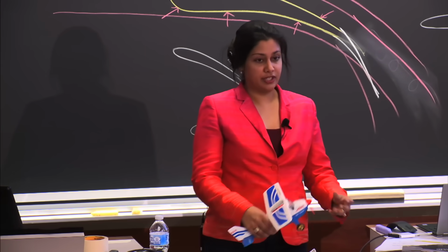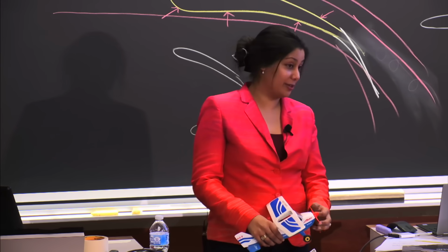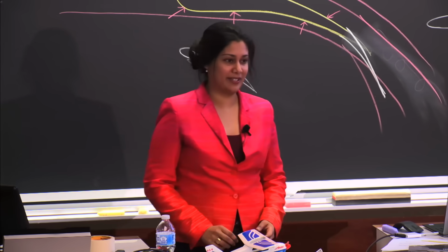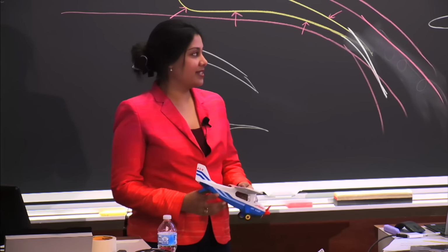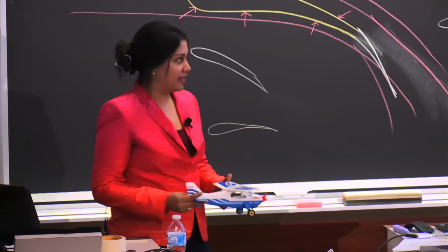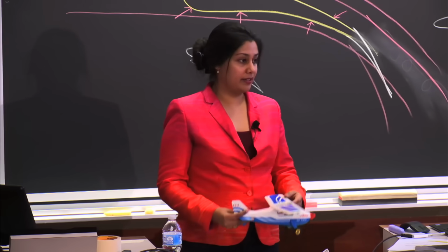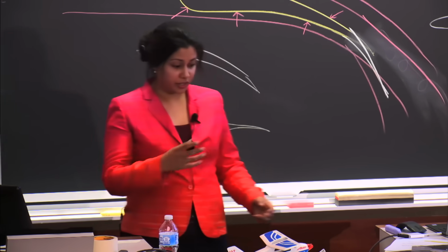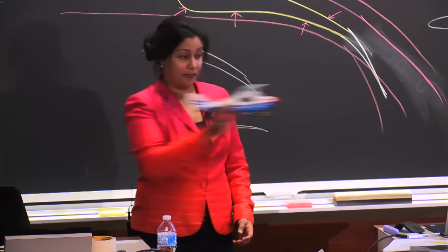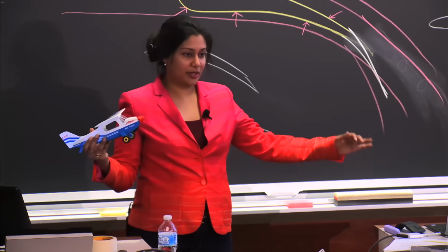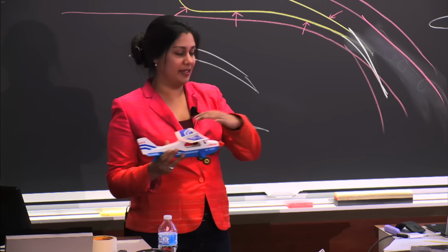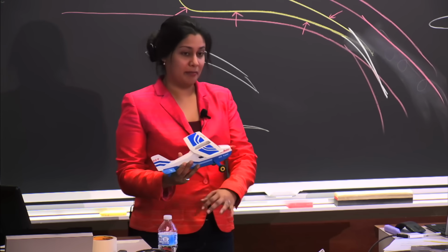Yeah, the reason that you, especially on landing, many times people use flaps on takeoff as well, but the reason is just that you like to have your aircraft configured that in case you didn't take off, you can land without making a lot of dramatic changes. The reason that you do that is basically that by increasing your lift, but also increasing the drag, drag affects how fast you're moving forward, right? And so you can actually have the airspeed be higher with the ground speed being lower.